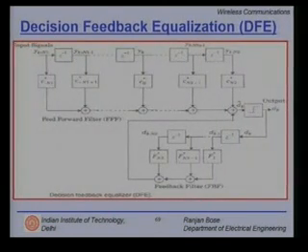This is the general structure of DFE. The input signal comes in here and then it is delayed as always. And then you have the complex weights Cn1, Cn1 plus 1 and so on and so forth. This is your feed forward filter, also called FFF. At this juncture you have a decision device, a thresholding device, and then you get an estimate.